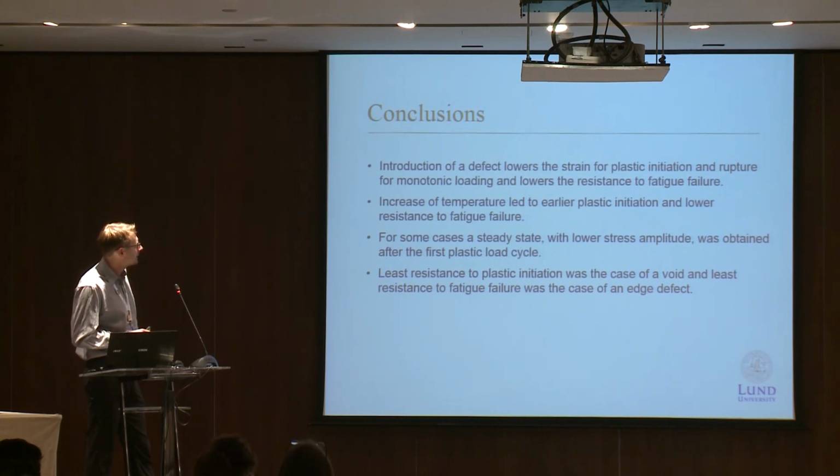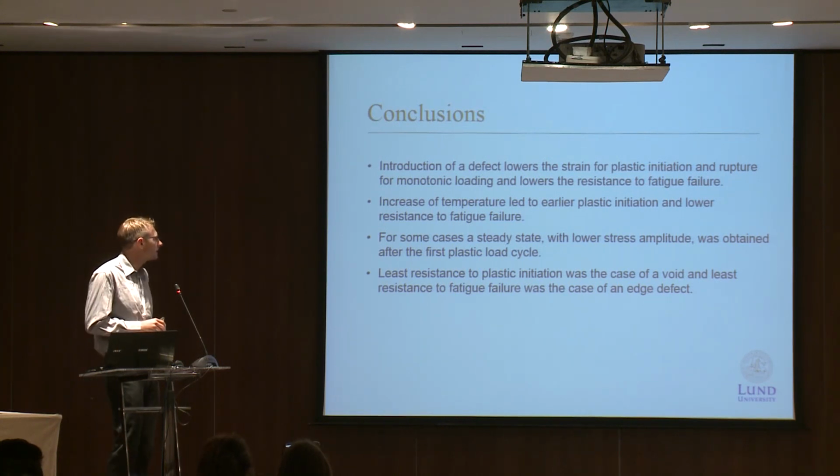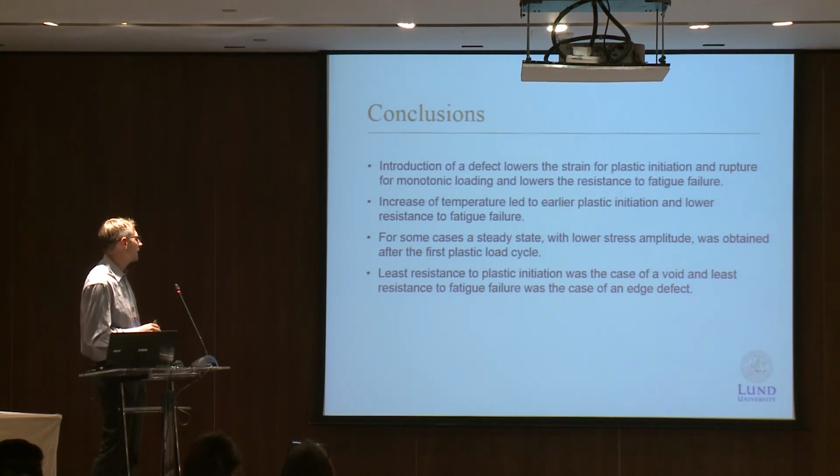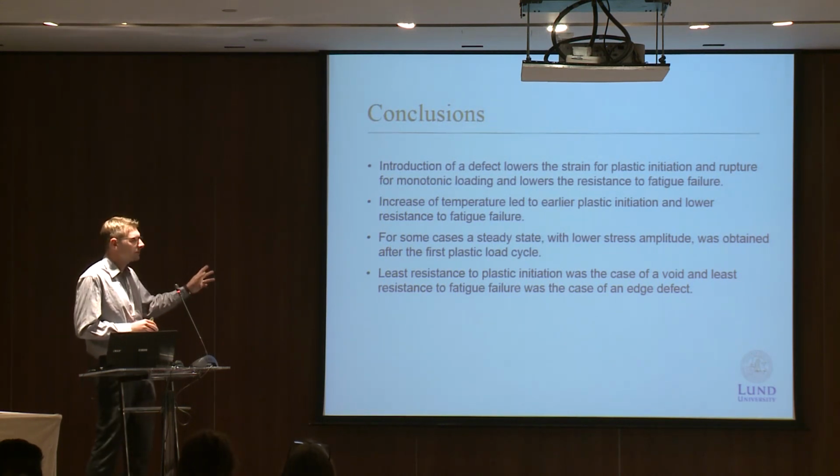Least resistant to plastic initiation was the case of a void, and least resistance to fatigue failure was the case of an edge defect, but these two were quite closely matched.